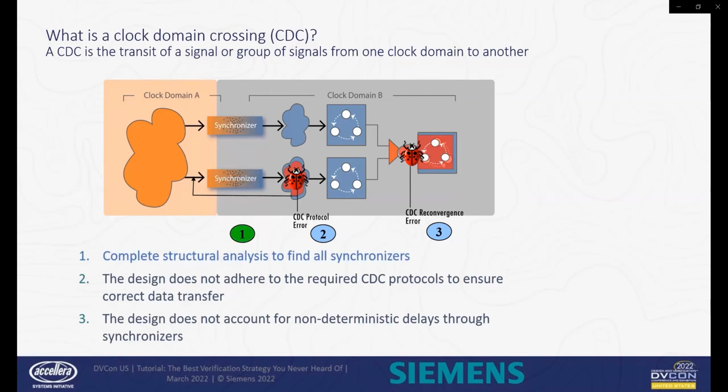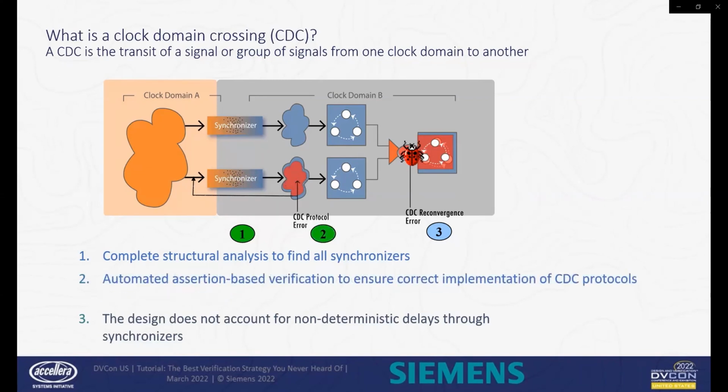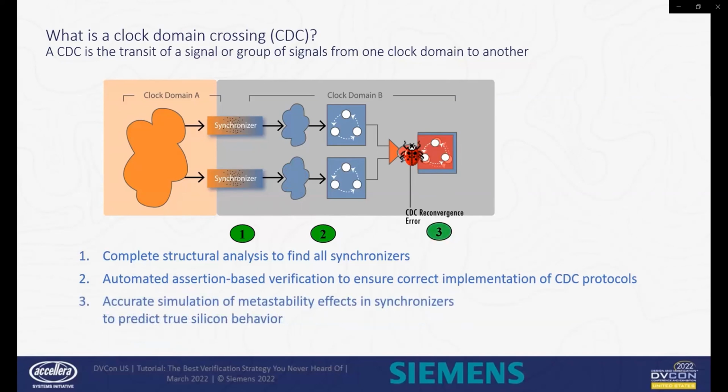Static analysis is used to verify these synchronization structures. Second, assertions are used to verify the protocol rules in formal analysis and simulation. And finally, metastability delay models are used to verify reconvergence in simulation.